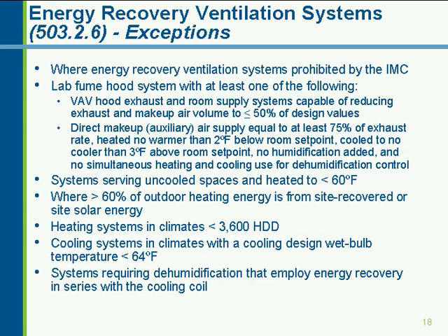There are a number of exceptions to the ERV, or energy recovery ventilator requirement. If energy recovery is prohibited for that application by the IMC, the International Mechanical Code, you're not required to do it. Examples of that would be spaces that are exhausting toxic fumes or kitchen grease hoods. If you have those types of applications, you're not required to do energy recovery from them.